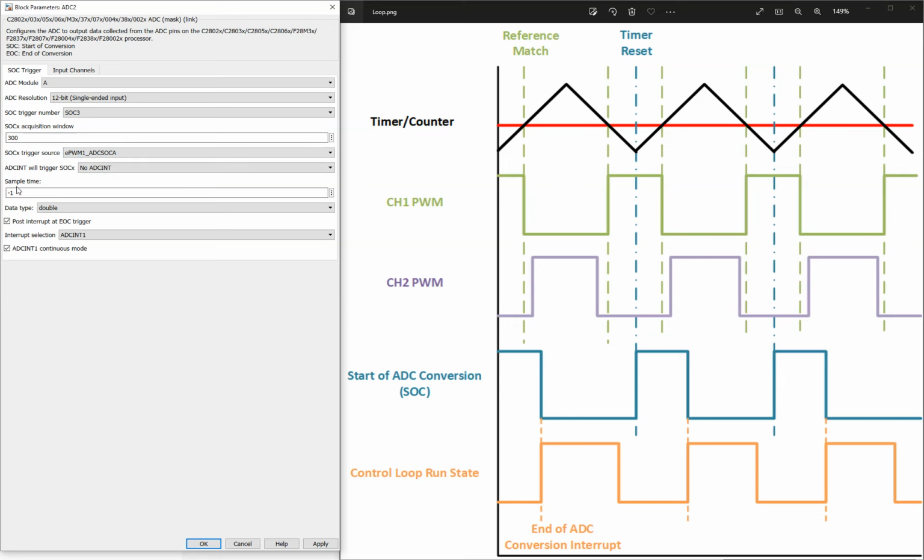After that we have the sample time. Because we are generally operating on an asynchronous event, the hardware interrupt, the model doesn't know when the hardware interrupt will occur, so we can't put a pre-estimated time here. So we are going to put -1 here.